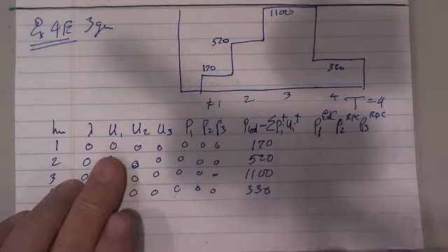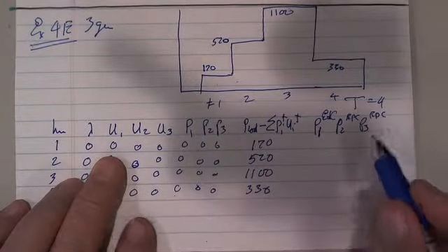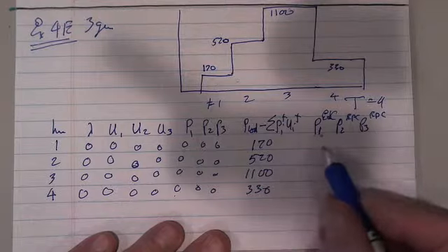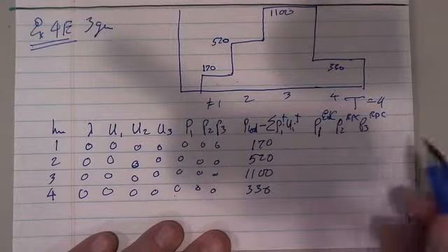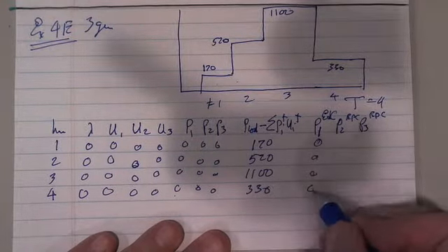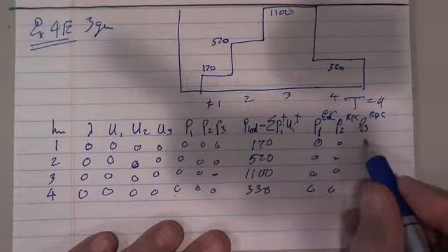If a unit is offline, meaning U equals 0, well then it will come up with a 0 for the EDC, but the other two will be in economic dispatch. Well, this is zeros for everybody, so this is the starting point.